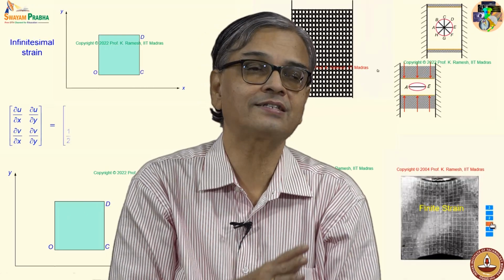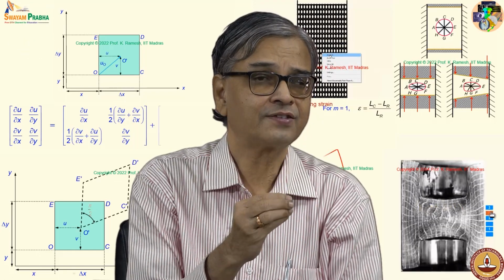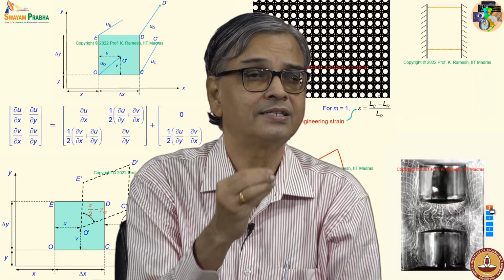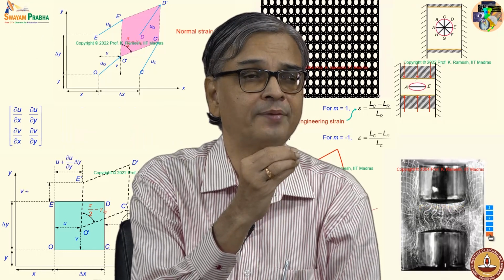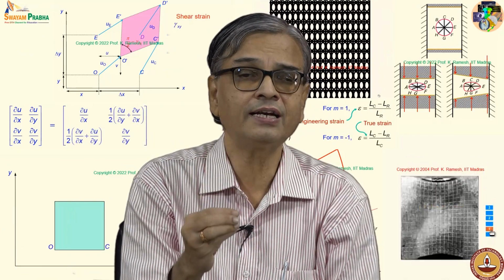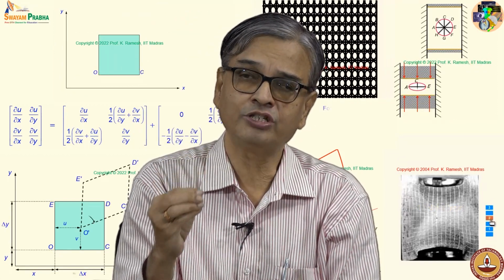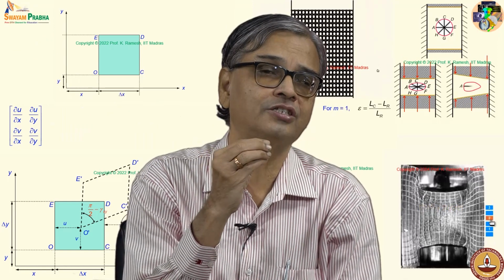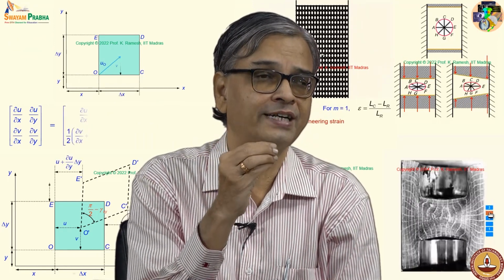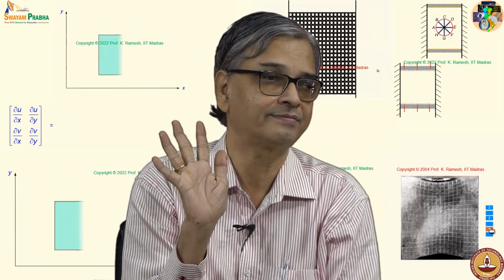So what you have to understand is, we have looked at stress from the original simple experiment of taking the material with 3 different cross sections. If people plotted on the x-axis change in length divided by original length, and in the y-axis force divided by area, you could get only one line for the given material.